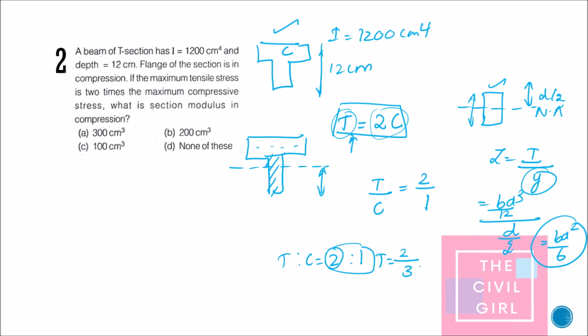I am sure you guys know the basics of how to find the ratio. It is 2 divided by 2 plus 1 into 12. So tension will be occupying a length of 8 centimeter, which is completely in tension. Total is 12, so the remaining will be 4 centimeter. So 4 centimeter is given to compression.